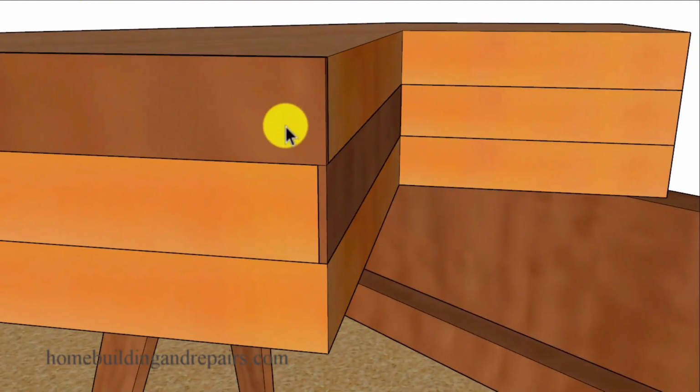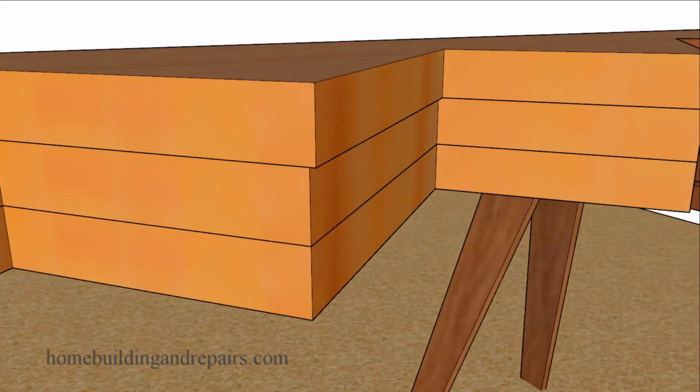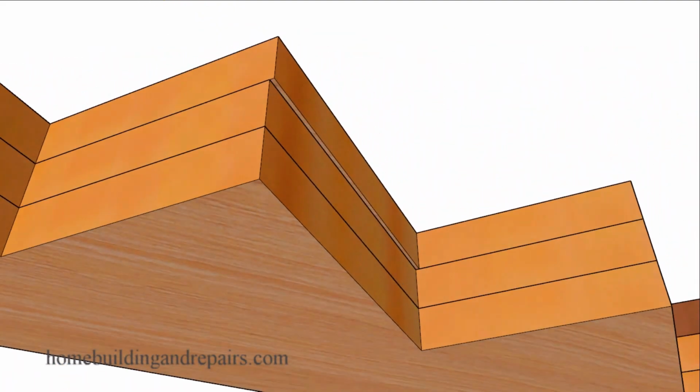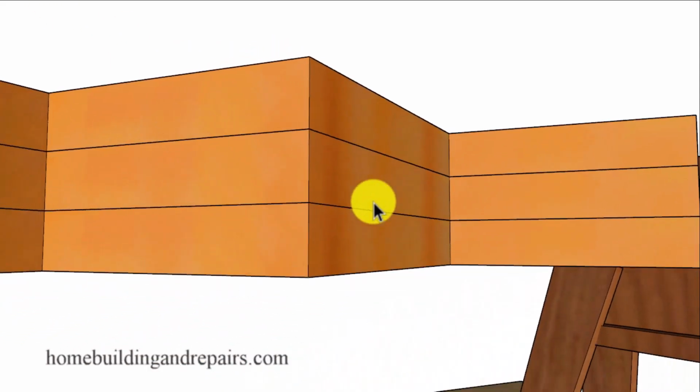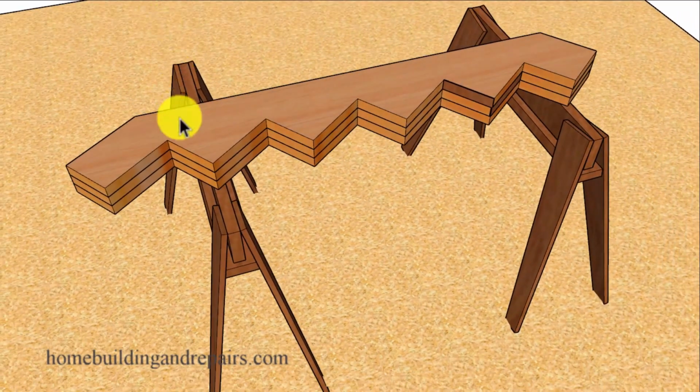So here we had some imperfections that needed to be filled, and we used shims to do that. However, you could end up with an imperfection like this that needs to be trimmed. And if that happens, just simply grab your saw and recut that part of the stringer, or use a planer or some type of a sanding device to trim the wood off. Now, I've also used belt sanders to flatten some of these imperfections out also. And the last thing I would like to suggest would be that if you have too many imperfections, then you might consider recutting the stair stringers.